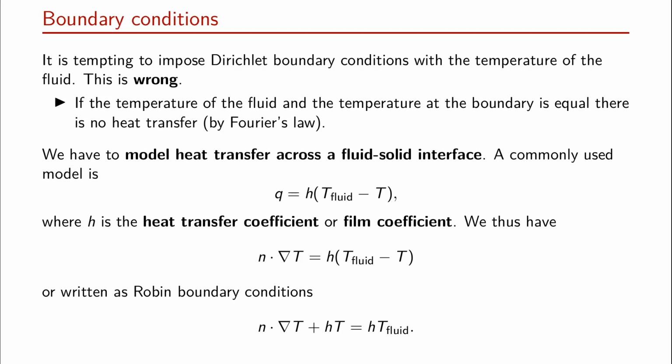Because we have a material interface there, on one side of the interface we might have the fluid, which has one temperature, let's say 20 or 25 degrees, and on the other side of that interface we have the metal, aluminum, which represents the heatsink. And that, even as we approach the boundary, will have a different temperature. So there will be a discontinuity in temperature across the material interface, and this is what drives the heat exchange.